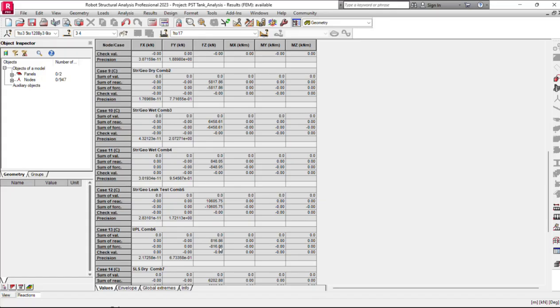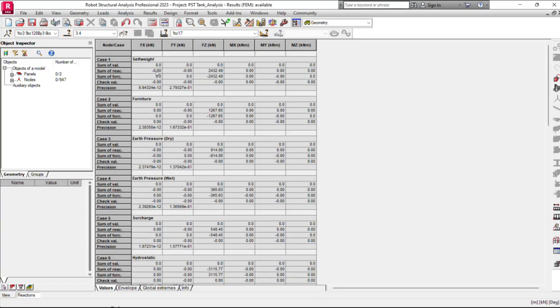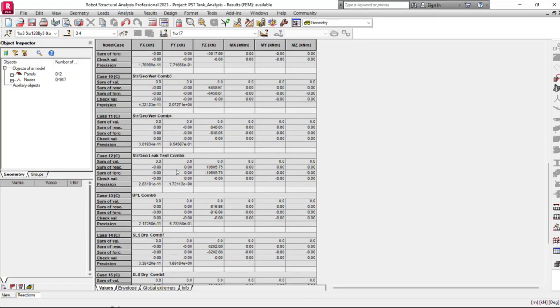So here, the summary of force is now negative, which means, let's go back here on the weight, which is always how we assess the signs. Basically, the summary of force is negative, and it's downward. So it means this is the weight of the structure. It's going downward. Then we go to uplift. It's negative 816.86, which is pretty much okay for now. All right, so it's already been solved. Uplift is okay. What's next?